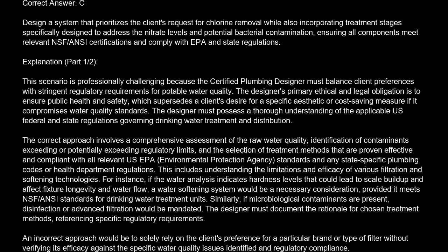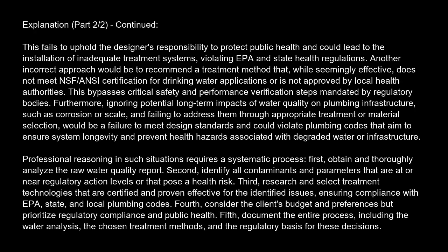An incorrect approach would be to solely rely on the client's preference for a particular brand or type of filter, without verifying its efficacy against the specific water quality issues identified in regulatory compliance. This fails to uphold the designer's responsibility to protect public health and could lead to the installation of inadequate treatment systems, violating EPA and state health regulations. Another incorrect approach would be to recommend a treatment method that, while seemingly effective, does not meet NSF/ANSI certification for drinking water applications or is not approved by local health authorities. This bypasses critical safety and performance verification steps mandated by regulatory bodies.